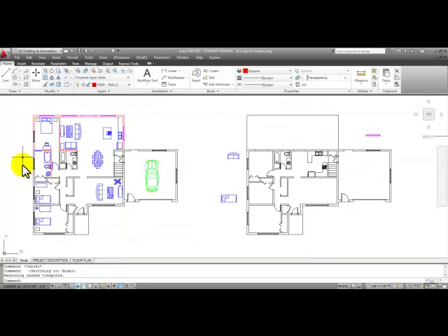This is only one option for creating a very quick addition. You can use your own layout or use this exact layout that I'm showing you in this video. So we'll use the offset command that we've been using in class. In the modify panel, I'll pick offset, I'll type in 8 and enter. Select here the outside wall and then pick inside this addition. Select this outside wall and this one here as an offset. We can right click and pick enter.